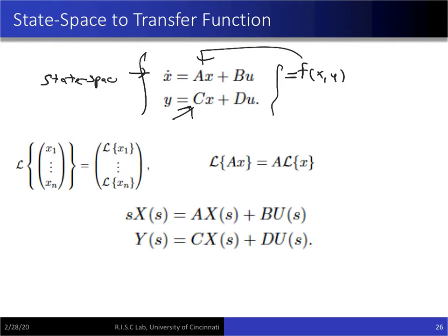Right? So now the idea is, let's say a system is given. Earlier, when we were doing Laplace, what were we doing? We were transforming higher order differential equations to transfer functions, right? But let's say you already know the state space form and don't know the higher order equations. How do we go to transfer functions? So if the state space form is given to you, how do we get a transfer function from that? Okay.